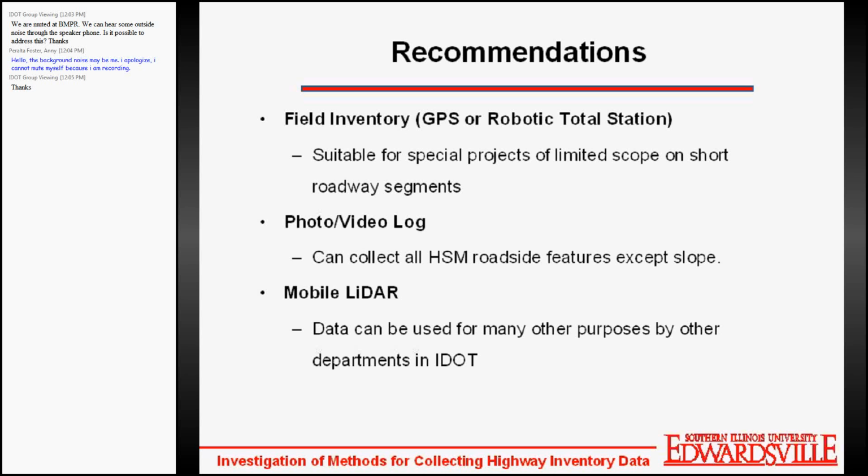One other thing I might add, Ms. Priscilla, is that there's also some additional equipment, for example to get pavement marking. You can drive through the job and it will use the LIDAR to locate your pavement marking and your pavement quality, where it's in place and where it's normal, and it can collect that data. Then when you go out to strike, you attach this piece of equipment to your truck, and it basically puts the pavement marking right back where it was. I have additional information on some different companies and equipment out there that I can provide to you and to Rob.